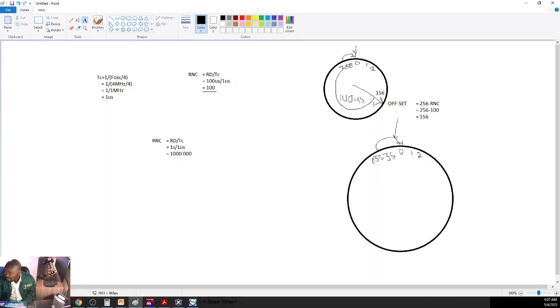But now, with a 16-bit timer, we can count up to 65,000, not 1 million. This is with a prescaler of 1:1. With timer 1, we have a prescaler of 1:1 up to a prescaler of 1:8. We now need to find out which prescaler we should use to get the count to be less than 65,536. Right. So to do that, we now need to go and calculate the minimum required prescaler.